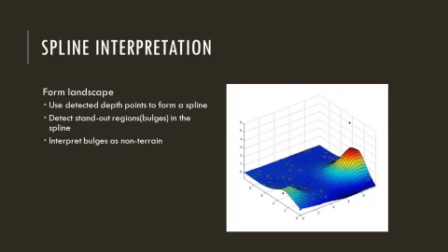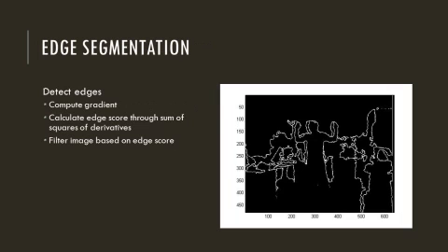This allows for the detection of bulges that find high-value spots in the depth data with ease. From there, it is a simple interpretation of these areas as non-terrain for further identification as either a machine or an object that should simply be avoided. There is still a need to test and integrate this into the overall project, and there is a possibility of slow computation proving too cumbersome, so this may be replaced with a quicker process as research continues.